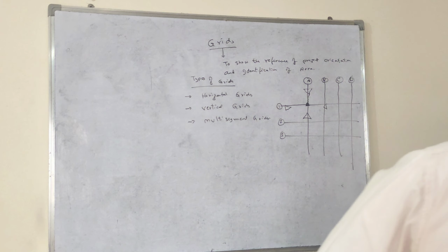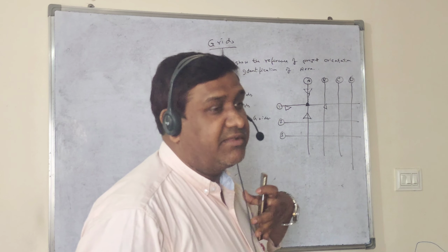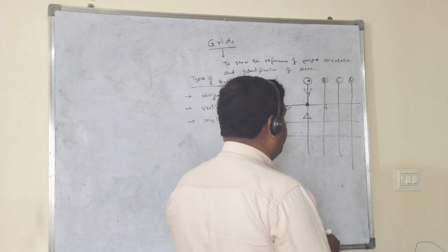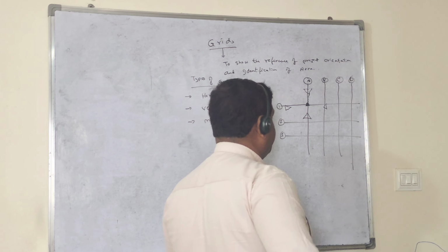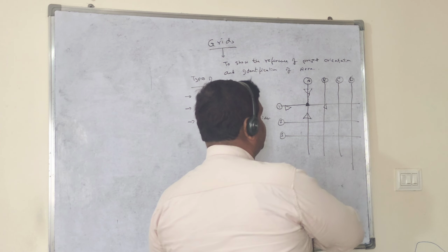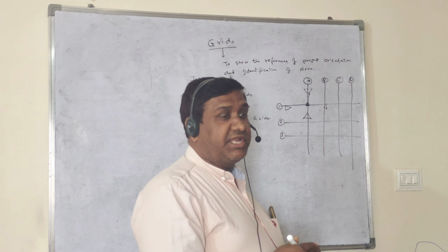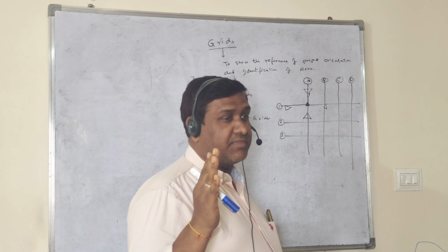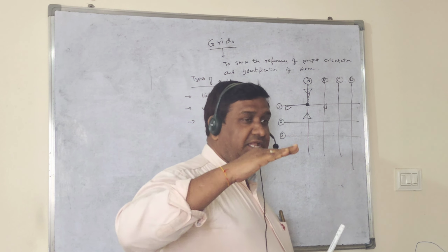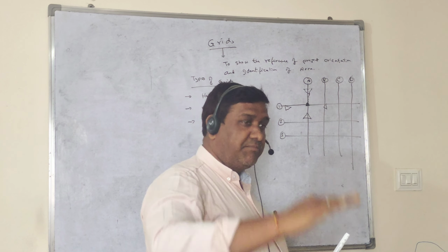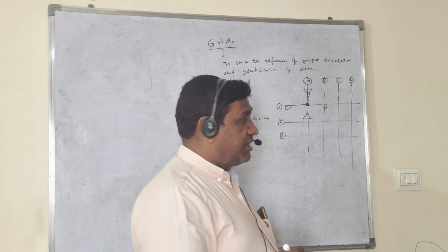Exactly, the grids will be centered on that project base point. So the vertical grids start from the vertical point of that base point, and gradually go to the right side of your project. And horizontal grids you can take at the top, or at the bottom also. Both sides are possible.